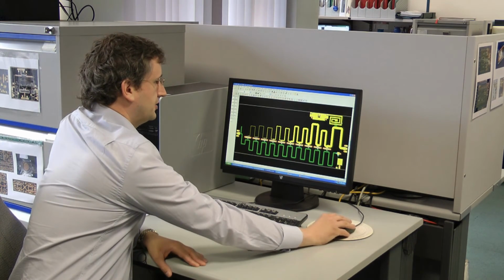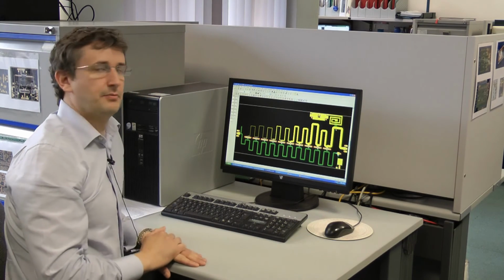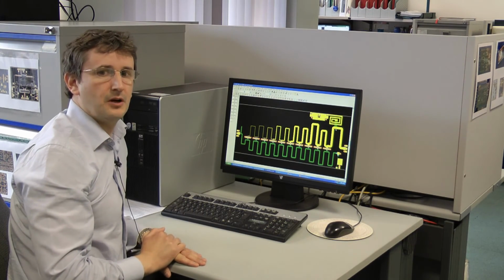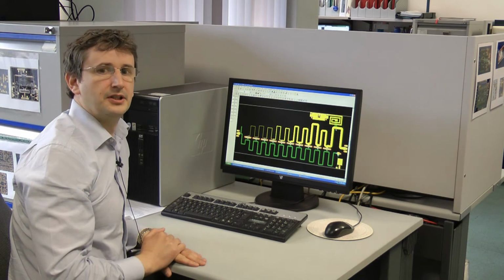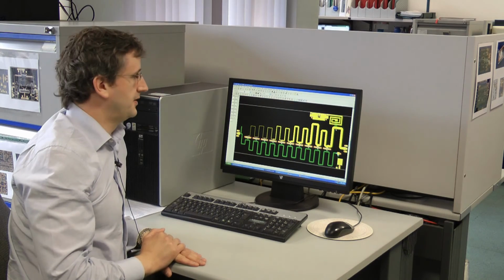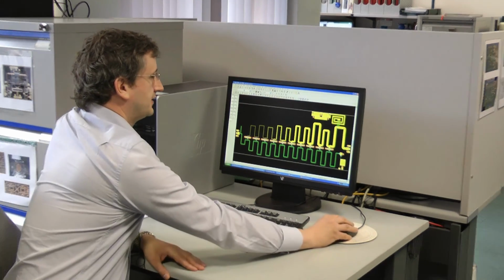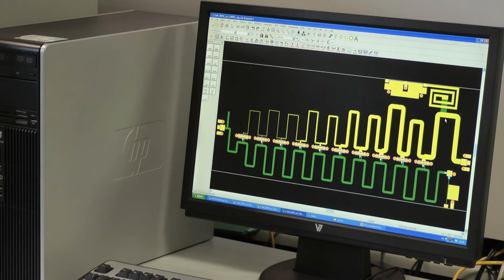Where the drain bias choke is applied is also significant. It is applied at the output, which is a low impedance point, so minimizing loading effects of this choke. Also, the drain line is at its widest, which is best for current handling and minimizing IR volt drops.